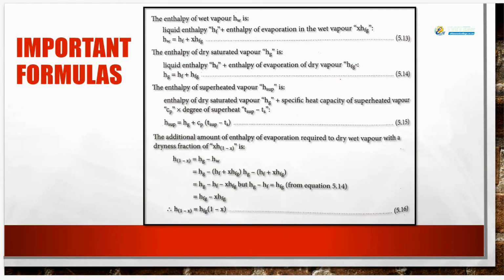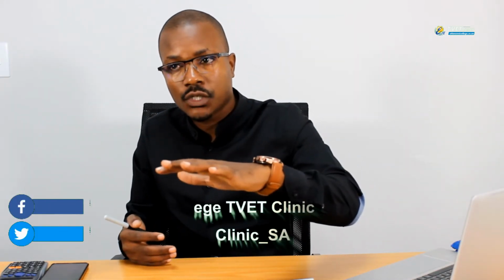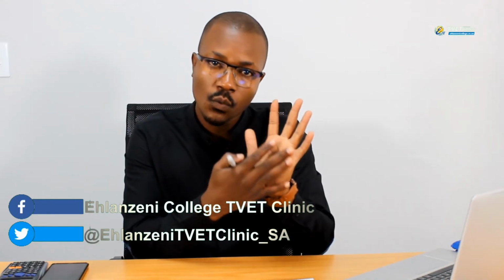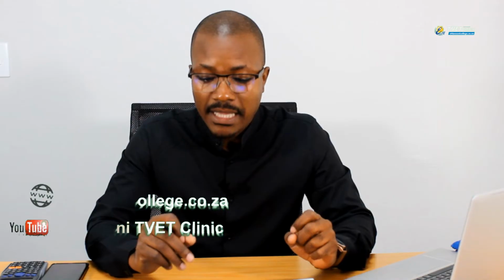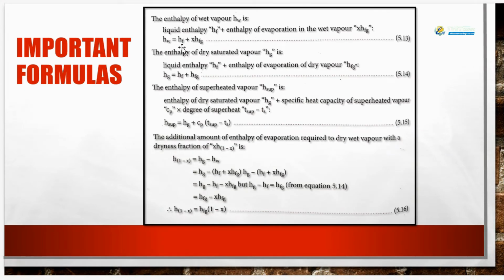We have the first one in 5.13. It's called the enthalpy of wet vapor. Remember, when we first produced our vapor or our steam, it's wet, such that if you have a pot with boiling water and you put your hand just at the top, you'll see your hand getting wet. That is called wet vapor. The equation to calculate the enthalpy of wet vapor is given as Hw = Hf + x Hfg.